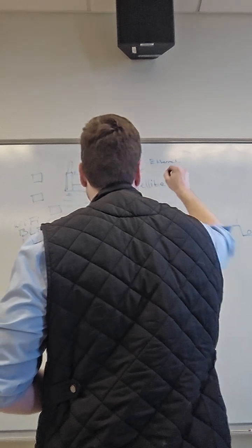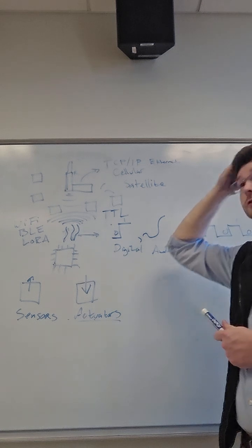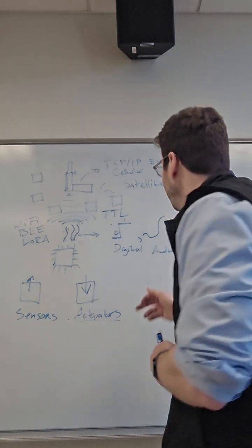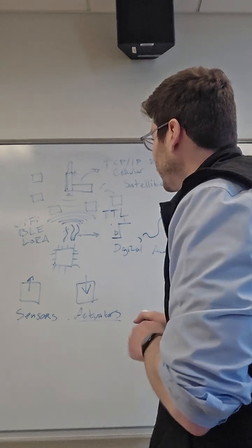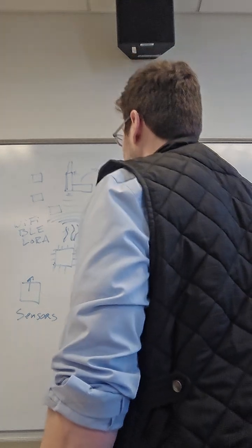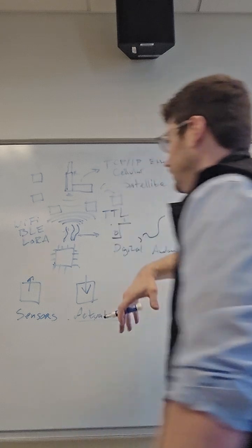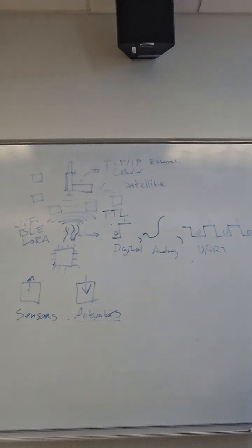Okay, I've done a couple of satellite contracts too, where they were really out there. They were actually on a shipping container, and they didn't even have cell out there in the middle of the Arctic, but they still needed to get cold chain storage information up to their network. So they did satellite backhaul instead, where they had a gateway on board that could talk Wi-Fi or BLE or short-range radio, right? To get the short hop from those devices to the gateway, and then backhaul, upload to the internet. Okay, so that would be stage 2 of our system, kind of the aggregation method.